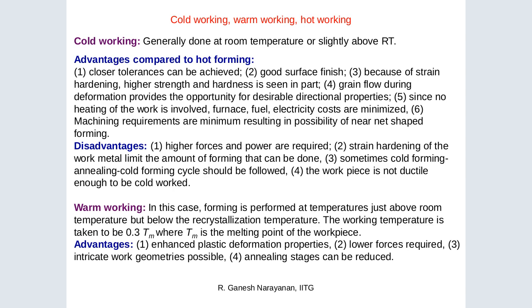Now we have cold working, warm working, and hot working. What is the difference between them, or what does it mean? Cold working is generally done at room temperature. That is the definition of cold working. It is done at room temperature, meaning without change of temperature, or slightly above room temperature, meaning you can heat slightly a bit.